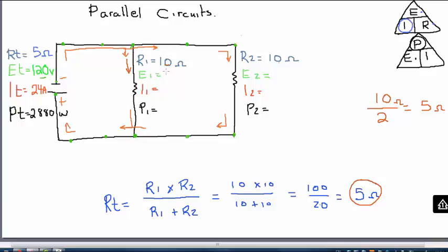That's just the extension of that voltage power supply wire. So we can say that our voltage is 120 volts here across that load, and our voltage is 120 volts across here, across load resistor 2. So that's fairly simple. We just go on the basis that in a parallel circuit, voltage remains the same, but current divides. So let's take a look at our individual current dissipations here.